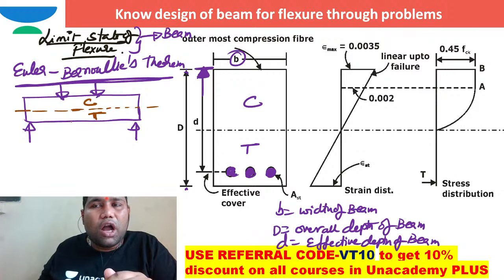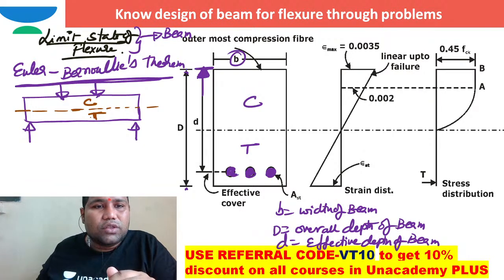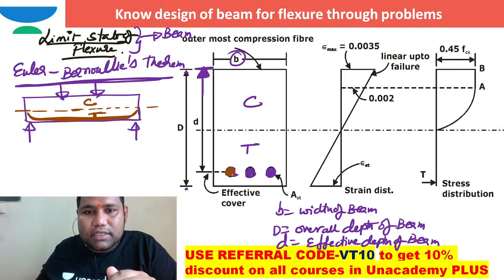As concrete is weak in tension, I need to provide reinforcement in the tension zone. That is the reason the area of tension steel is provided on the tension side in this way. This is the main tension steel, the area of steel in tension.